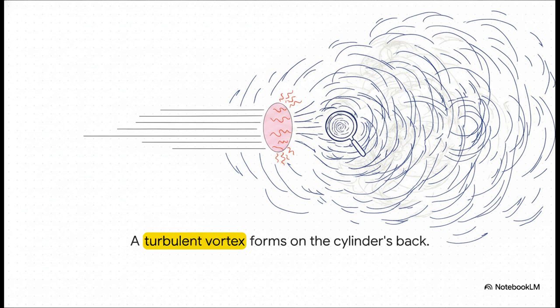Notice how the flow rolls back onto itself in the wake, creating these swirling vortices? This means you've got smooth, predictable heat transfer on the front of the cylinder and chaotic, turbulent heat transfer on the back. It perfectly encapsulates exactly why we need robust empirical data. Pure math alone would seriously struggle to cleanly model that swirling vortex wake.